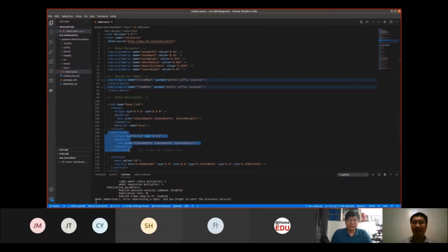Over there, as long as it is big enough, I mean the robot, we can't make it larger than it is, because we need to make sure our robot can pass through a tight door. We cannot make the safety distance for object avoidance too big, because that would make our robot unable to pass through certain corridors or doors. But I'm not sure if that is defined in SDF. Yes, that is defined in SDF. Okay, right. The door itself and all of that, you can define in the SDF. Okay, right.